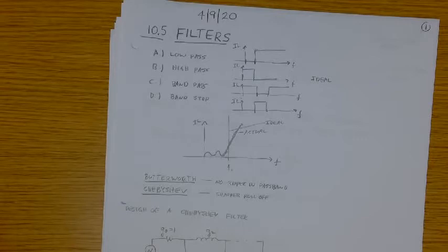Another application is to eliminate an interfering signal through a band stop filter. A lot of times when you make measurements, 60 hertz radiated from the power lines, or multiples of 60 hertz, 120, 180 hertz, on up the spectrum, might be causing some interference in your circuitry, and you may want to put a narrow band stop filter around some frequency that's causing interference.